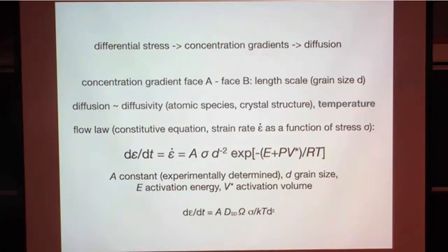You can see that you still have this A in here. In the end it becomes semi-empirical because we measure what we can and then fit these other parameters. In particular, A sweeps up things like the D_S naught, the initial self-diffusion coefficient, atomic volume, and so on. It's all swept into this parameter A that we just measure experimentally, right?